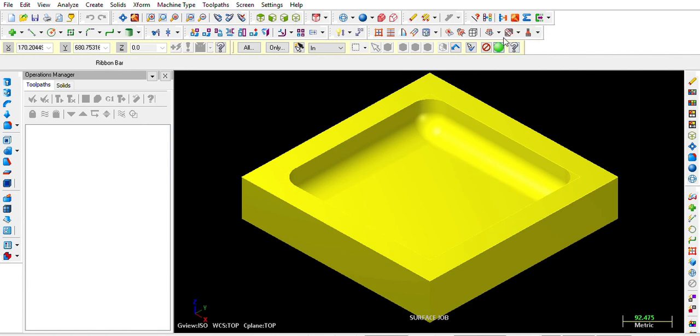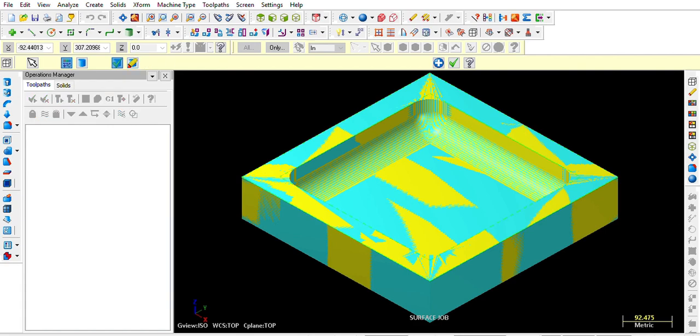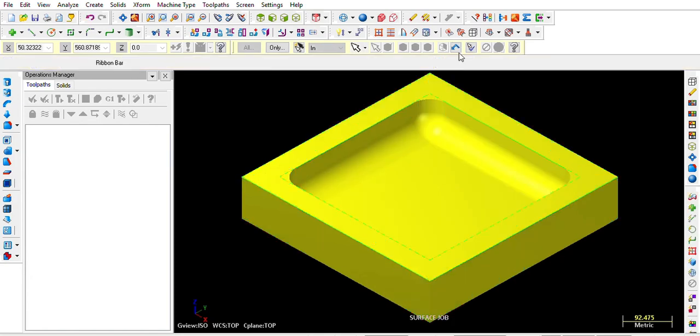So this lines. So I will just change the color of this one to this one. Okay, this is still a solid object. Okay, my mistake. So I would create a surface from solid. After then I'll be able to remove the solid. So create surface from solid. Okay, and I would pick up this solid object instead of face here. So now selected. So delete. So this is the delete option. So I would delete this solid. Okay. So now there is no solid inside, and it is a totally surfaced object.